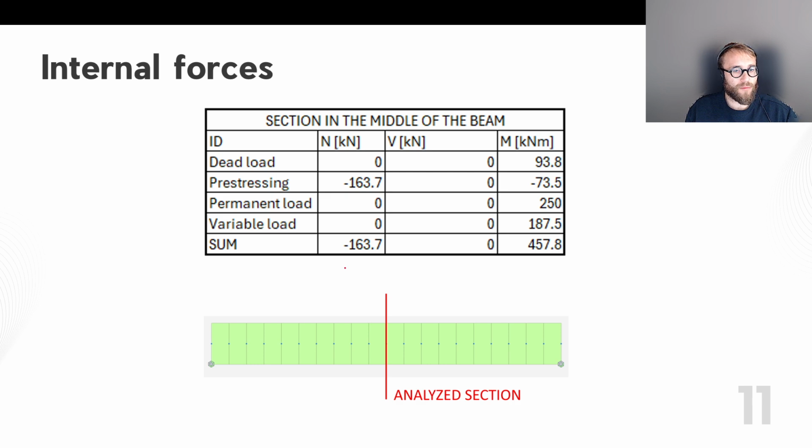In the 1D model, if you analyze the area where the linear plane of strain is violated, close to the discontinuity region where this plane of strain assumption is not valid at all, you will receive completely different results compared to IDEA StatiCa Detail, because the beam solution method is insufficient for this discontinuity region.